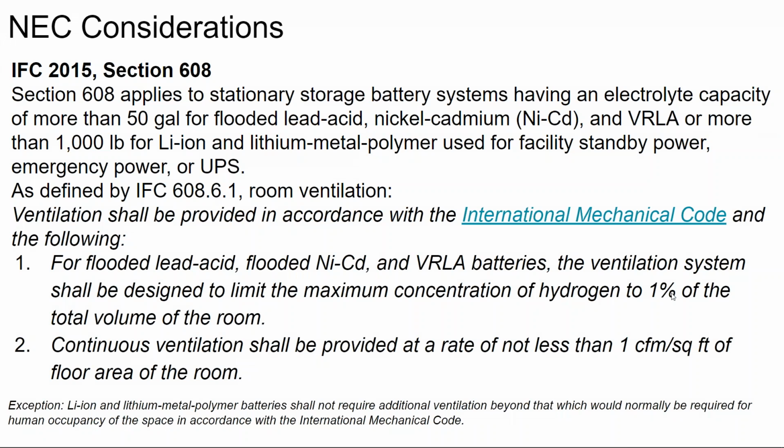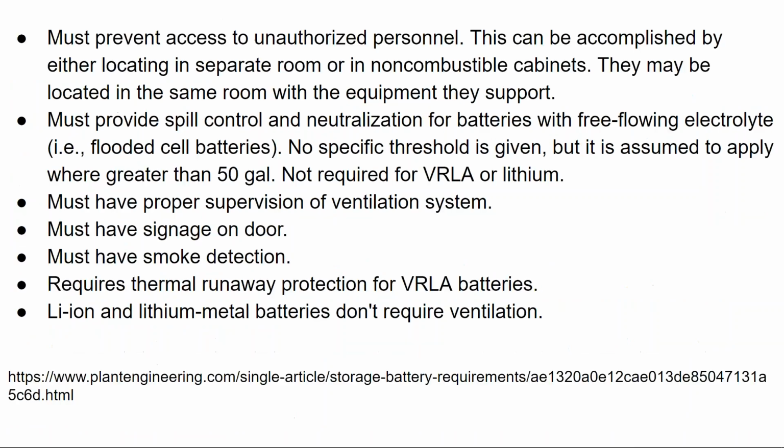Technically, an air-conditioned room is a ventilated room. And so IFC is saying you have to do a little bit more than just put your unsealed lead acid batteries in an air-conditioned room and say that because you have air handling units inside the room, it's ventilated.